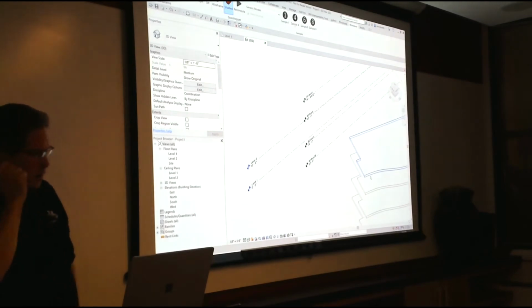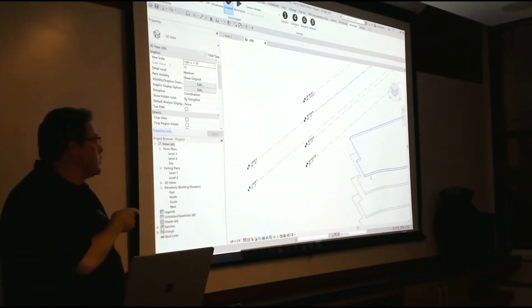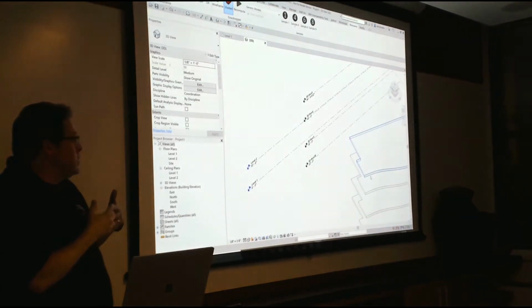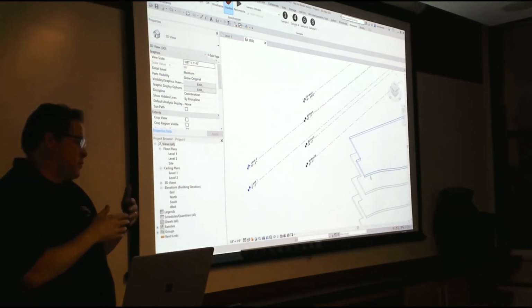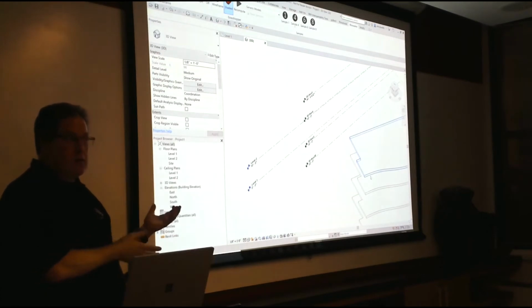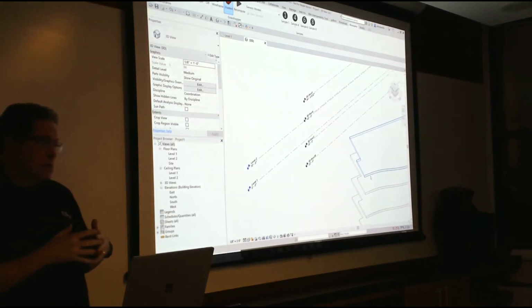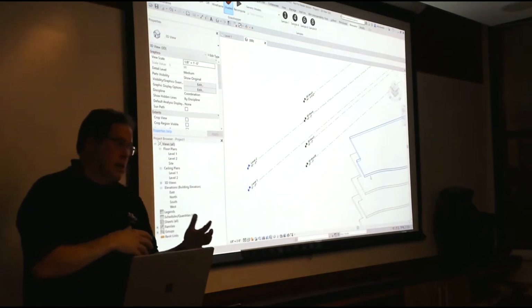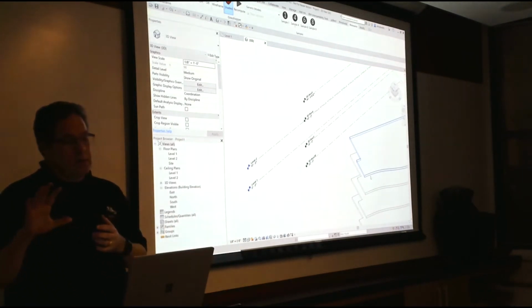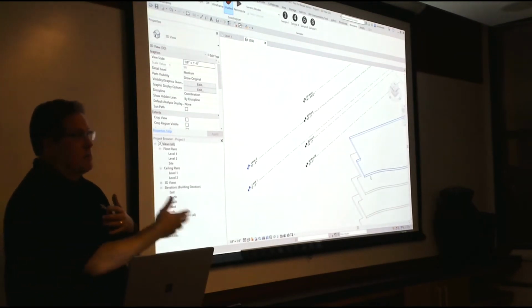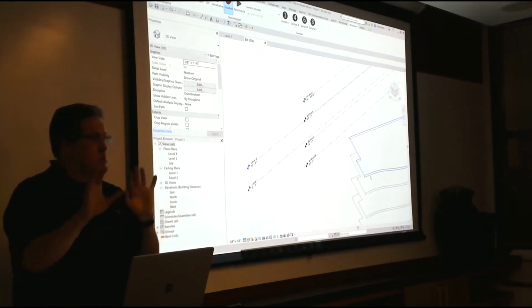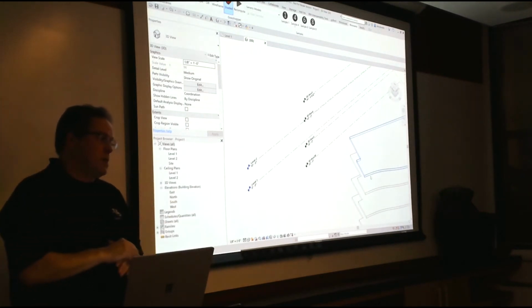Now, where we're coming from is really trying to help Rhino and Grasshopper users get into Revit. And the thing that we're finding interesting about this interface is that you can now granularly make that change almost on a project phase basis. So it may start as a lot of direct shapes, and then you're getting your floors across the system floors, but the facade is still a direct shape. And then you want your facade, so now you're running your facades across, and then sometimes you want to bring information from Revit. You want your grids and your levels coming back this way, and you like the core. Core worked out great in Revit, so now you're bringing your core across, and so you're actually going both ways, and that may adjust based on where you are in these different projects.